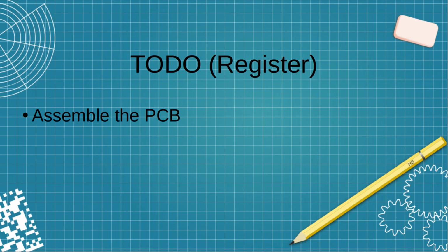So next up is going to be assembling at least one of the 16-bit PCB registers and getting that integrated into the build. Now, there is a component of this that I did not consider quite yet, but we'll have to do some research and figure out how I'm going to handle it. The TTL outputs are compatible with CMOS inputs. The CMOS outputs, on the other hand, are not compatible with TTL inputs. And I believe there's a way you can handle that by using pull-up resistors and the like, so I'll have to figure out exactly how I'm going to get that wired up.